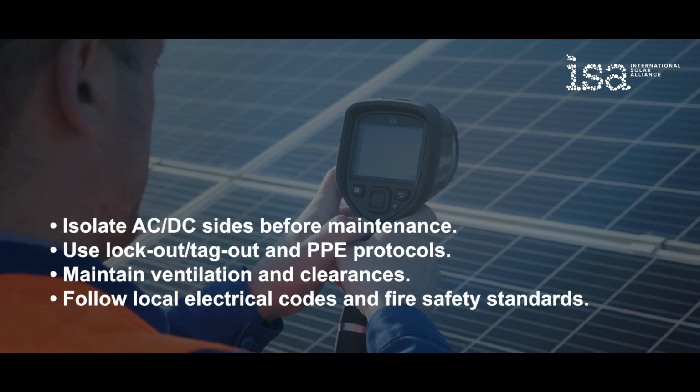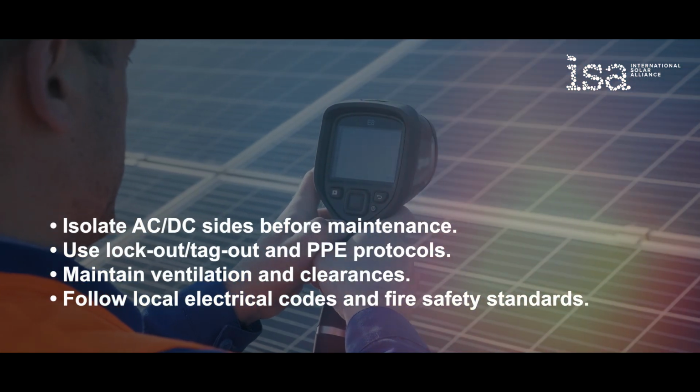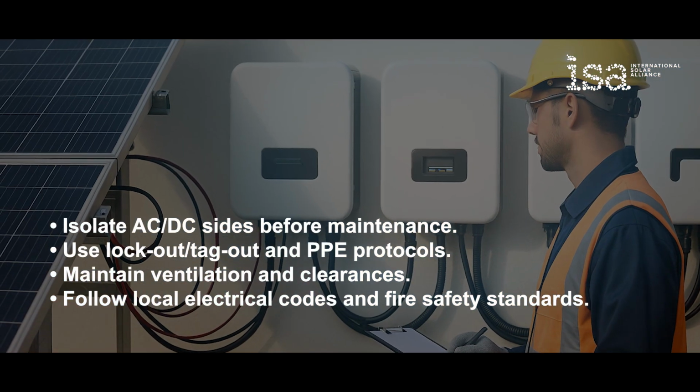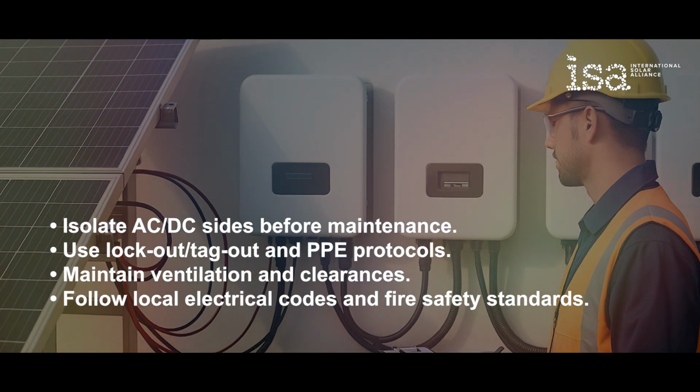Isolate AC and DC sides before maintenance. Use lockout/tagout and PPE protocols. Maintain ventilation and clearances. Follow local electrical codes and fire safety standards.